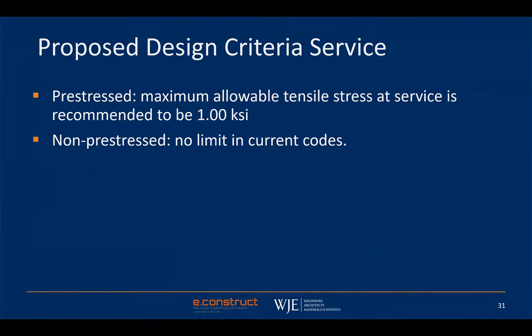Service load is very straightforward, nothing special. All you do is service stress analysis using the codes that you have, in Service I for compression, and check that the tensile stress is less than 1 KSI. Remember, cracking is 1.5. So we're taking a cut of 1/3 of the 1.5, and we're saying, just limit yourself to 1 KSI. That's more conservative than what we do with conventional concrete.